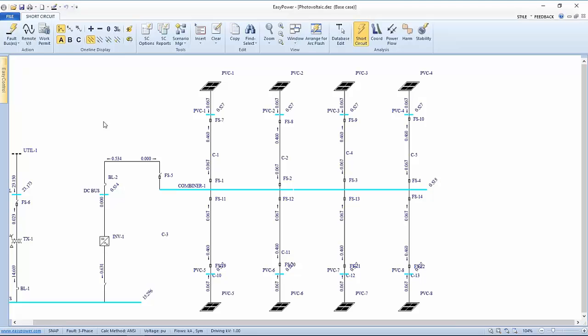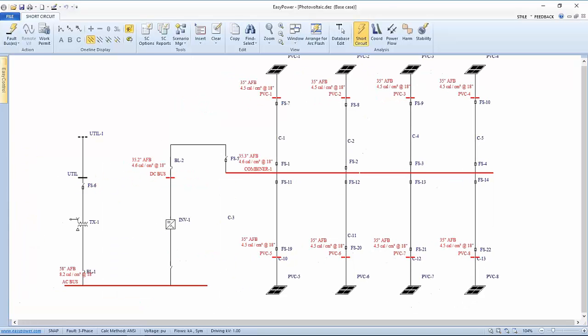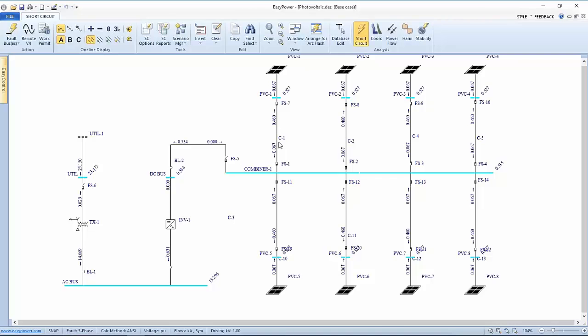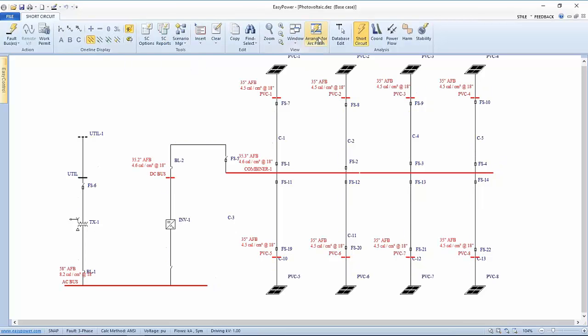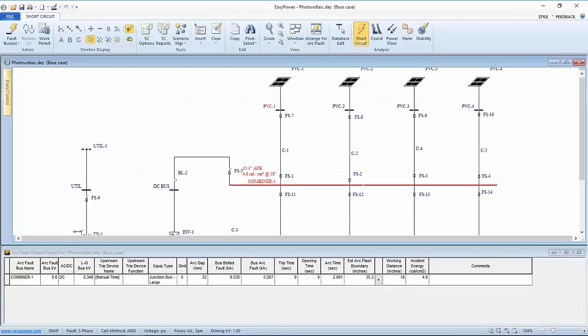So I haven't talked about the inverter yet. And this shows that even at the current we have, and probably because of the current, we're only talking 67 amps, there's relatively high calculated incident energy. If we look at, say, one bus at a time, we're seeing a total arcing current of 267 amps, and a maximum timeout on the calculations of 2 seconds.